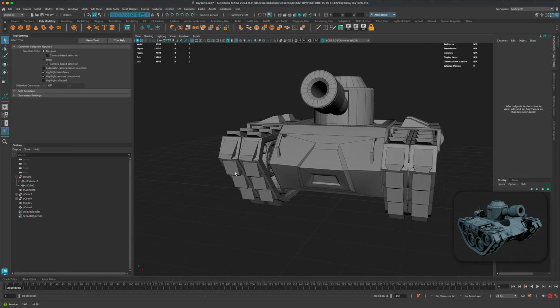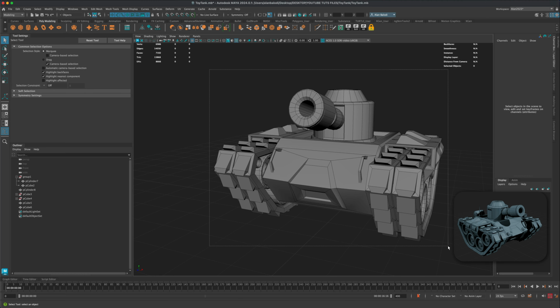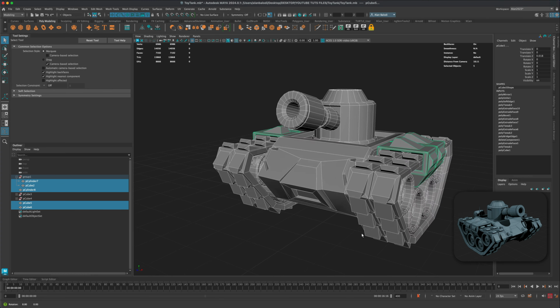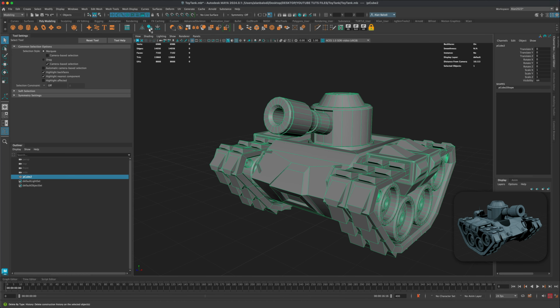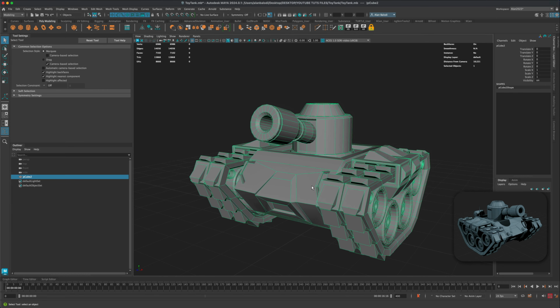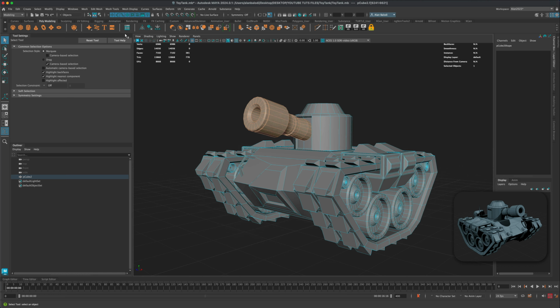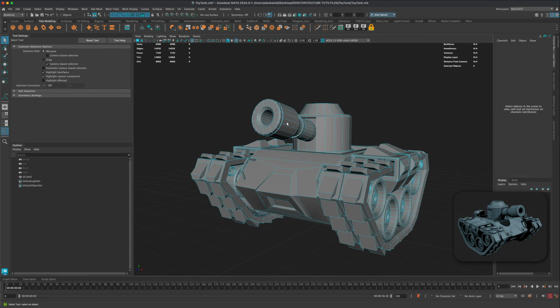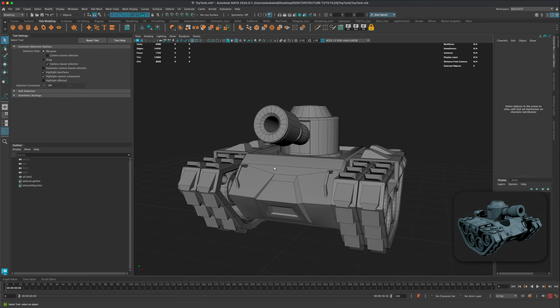Another thing we can do is, if you take a look at your outliner, you should see quite a mess, right? So if you wanted to, we could select everything, merge them into one shape and clear our history, so we just have one to deal with. And at any point, if you ever want to disconnect anything, it's very easy. You just select the shape that you want to disconnect, go to Mesh and do a separate, and you can see now they are separate meshes, right? So we have full control. I'm going to undo and keep them together to keep it nice and clean, right?